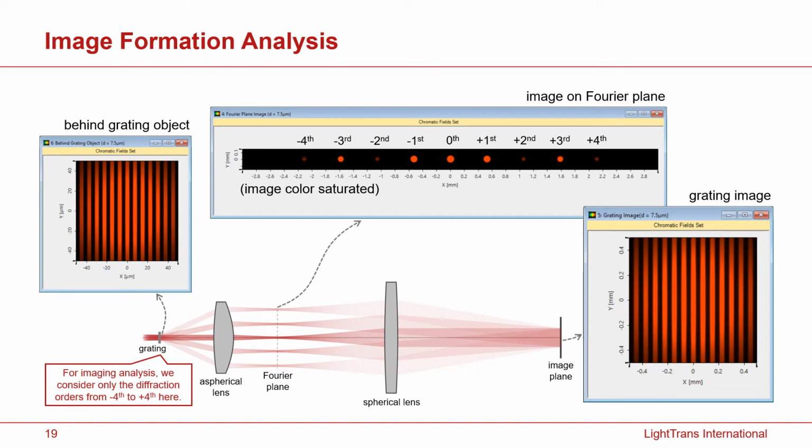And here we see the distribution of the different diffraction orders. As is well known, you have a very strong zeroth diffraction order and the minus first order, but the second order is obviously darker. I just want to mention that in our simulation, the grating can be modeled rigorously by using the RCWA method, and therefore we have exact access to the grating diffraction efficiencies. Here in the Fourier plane, you are seeing the brightness of the spots according to the diffraction efficiencies.